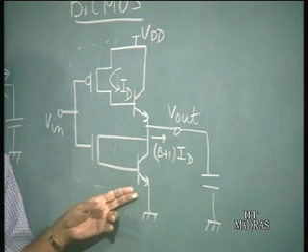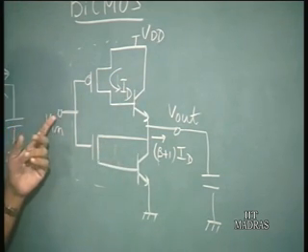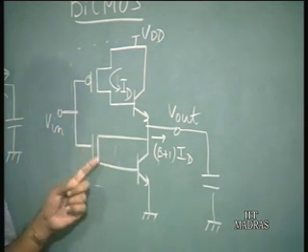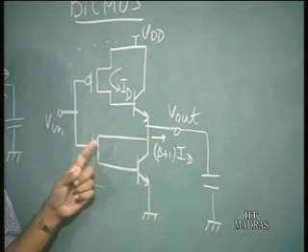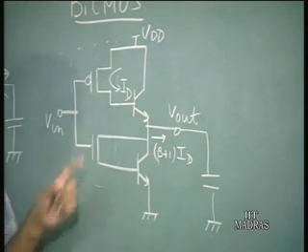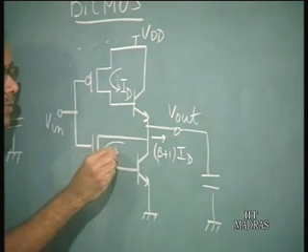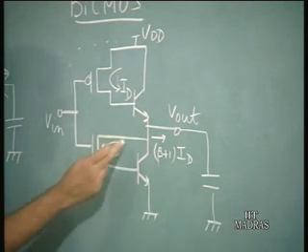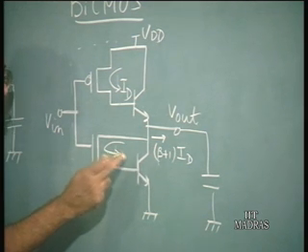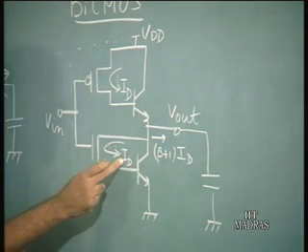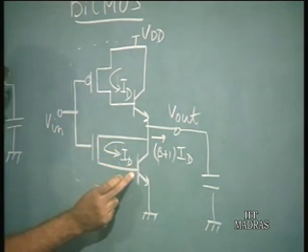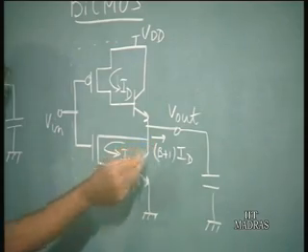On the other hand, if you look at the other situation, when the input is high, say VDD, then you have a high gate voltage for the NMOS transistor here. So, this NMOS transistor is on, whereas this PMOS transistor is off. Now, since this NMOS transistor is on, a current would flow in this direction. Again, this current is going to be the base current of this bipolar transistor, and since we have a current ID, which is actually the drain current of the MOS device,